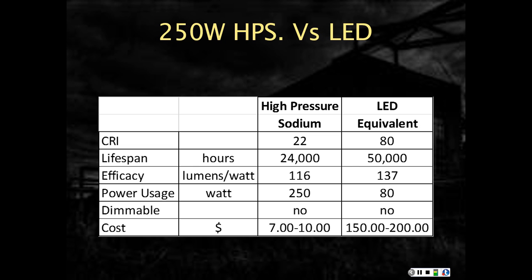On the next slide, we're going to compare an LED equivalent to a 250 watt high pressure sodium that you would typically see in a high bay area, possibly in a warehouse where color rendition index wasn't important, or out in a parking lot. 250 watt high pressure sodiums are very typical in parking lots.